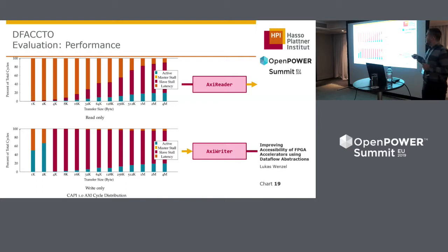And we see here the situation that those components are reading a consecutive buffer of memory of varying sizes, or in this case, writing this consecutive buffer of memory, and we have a trace of which clock cycles were passed during that time. So we have active cycles. These are clock cycles where actually a piece of data is moved from one place to another, so when this data stream shifts one piece of data out.